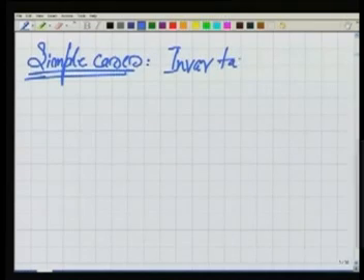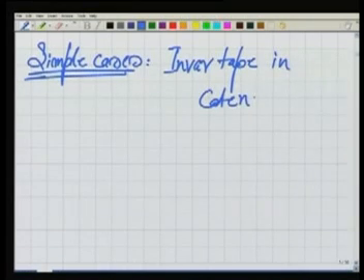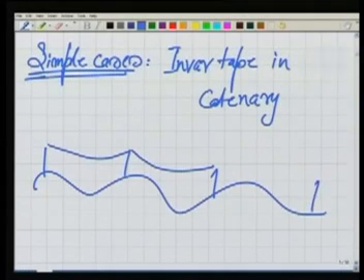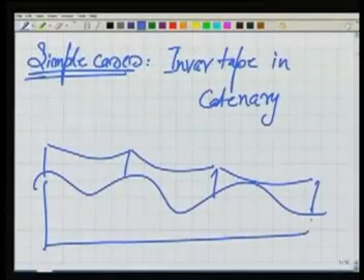You know the use of invar tape, why we use the invar, and in catenary. Now you know what is the meaning of that. We discussed that. We will be using the invar tape in catenary, and we will be applying all the corrections for all the kinds of errors. Then only we can determine the horizontal distance between these 2 points.